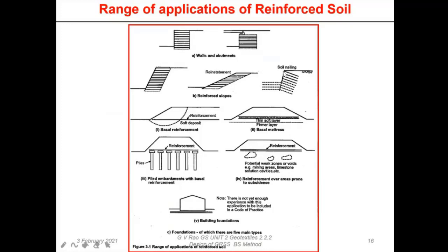Here what we are doing, we are putting in the reinforcement as you keep cutting. We introduce a rod or whatever it is. It's called a nail. It's not such a small nail. It's very long in length and large in diameter. And we keep doing it as we keep going down. We keep applying more and more as we keep cutting. So that is what we call soil nailing. And the reinstatement of failed slopes, and then a steep slope.